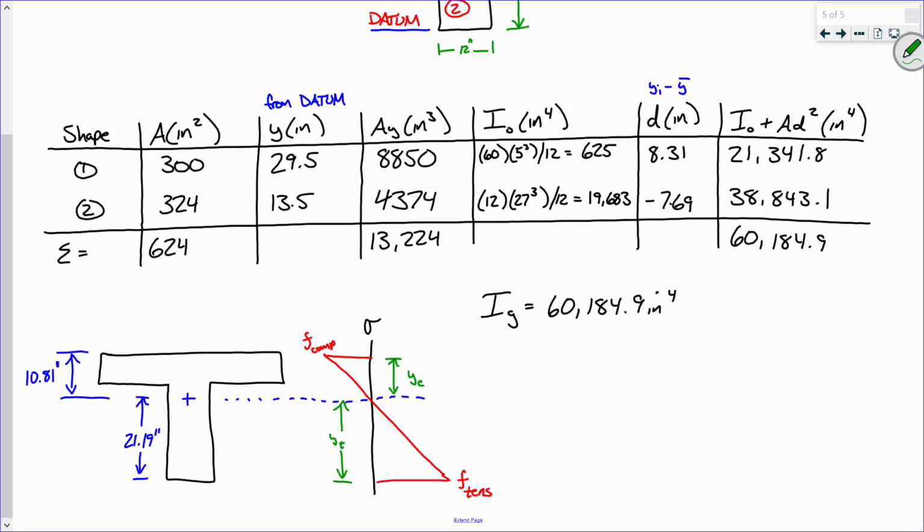Yeah, and if I bend this beam, the top's going to be seeing compression. Typically, the bottom's going to be seeing tension. We're just considering the bottom of the beam to be our tensile. That's very typical for a beam like this, because ultimately this T portion would be a portion of the floor slab. You see what I mean?